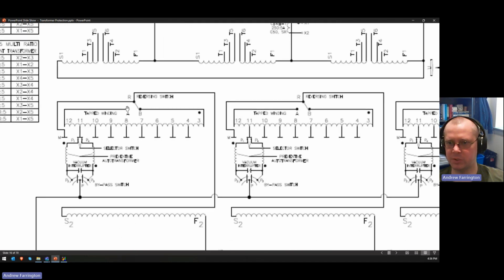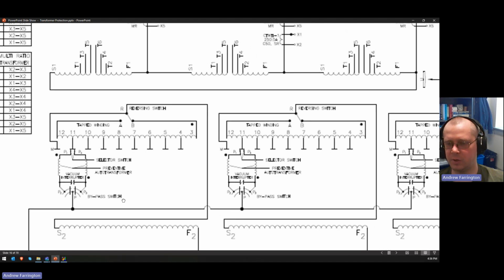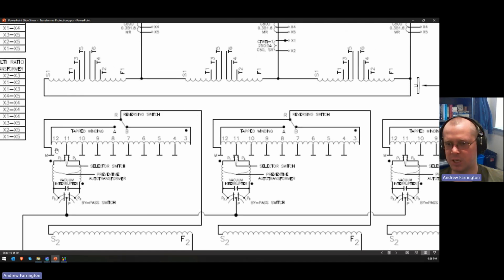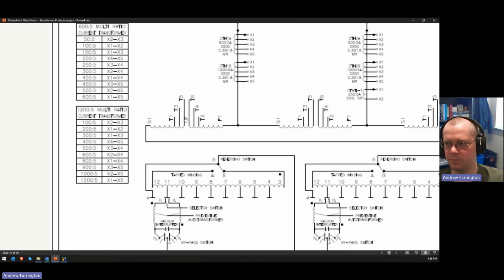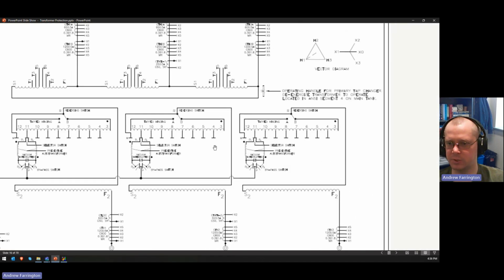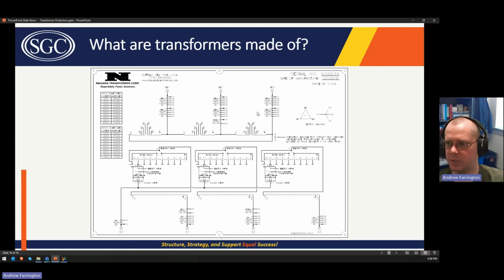And then this is a picture of the load tap changer, and it's obviously simplified, but basically there's a selector switch which gives you either raise or lower, and then this will just change the taps to deliver all of the different possible voltages that are available with the LTC.